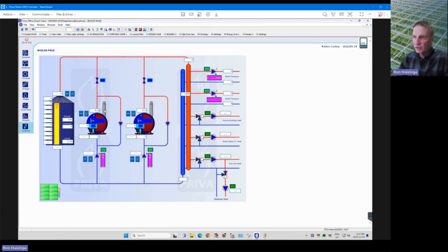So how the computer actually calculates this is it wants 90 degrees out here. So to get 90 degrees out, say your burner is running at half flame, 50% flame. So at 50% flame, we want 90 out, so we say we want 80 degrees in the back of the boiler. So to get 80 degrees, we speed up and slow down this pump to mix the 40 coming here with the 90 coming around here to get the 80 degrees back here.